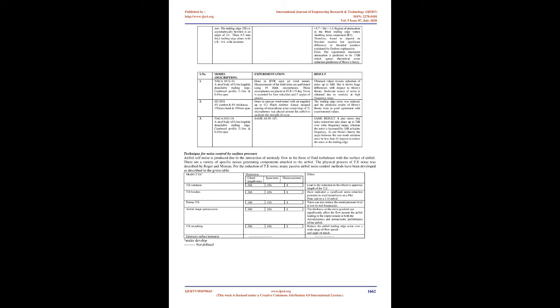The main objective of this work is to determine whether multiple mechanisms of broadband noise reduction can coexist on the Poroserrated trailing edge. Good broadband noise reduction can be achieved at high frequency, but vortex shedding tone at low frequency could not be completely suppressed at high velocity when sawtooth gaps are filled with porous material of low flow resistivity. When the sawtooth gaps are filled with porous material of high flow resistivity, no vortex shedding is present, but the serration effect on the broadband noise reduction becomes less effective.